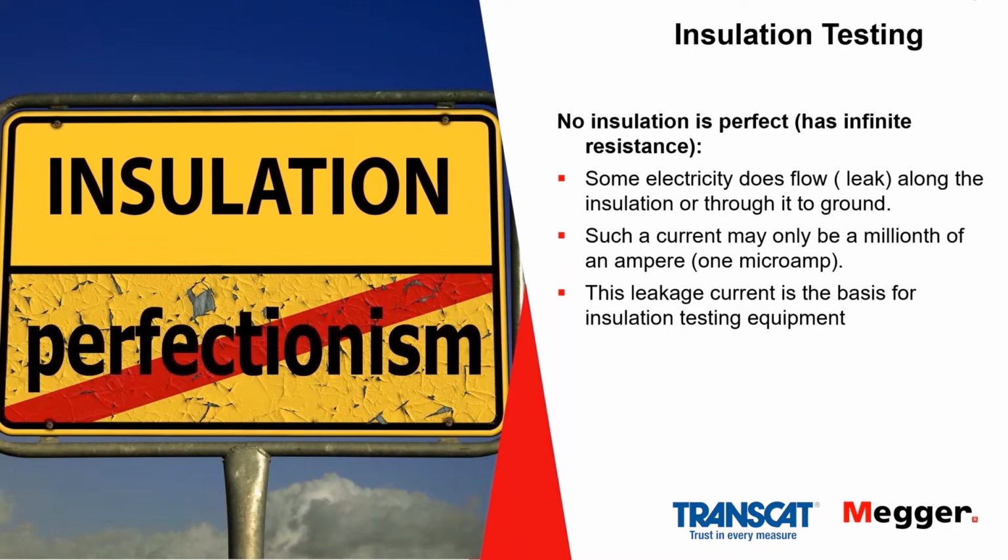Those old testers, and a lot of common ones still on the market, go to about 1 or 2 gigohms, which is 1,000 megs. So typically you'll get 1 or 2,000 megs out of a fairly off-the-rack insulation tester. At that rate, the common lexicon that got into our market was thinking in terms of infinity, as if that represented some sort of perfect insulation, but it doesn't. It's just an overrange symbol.